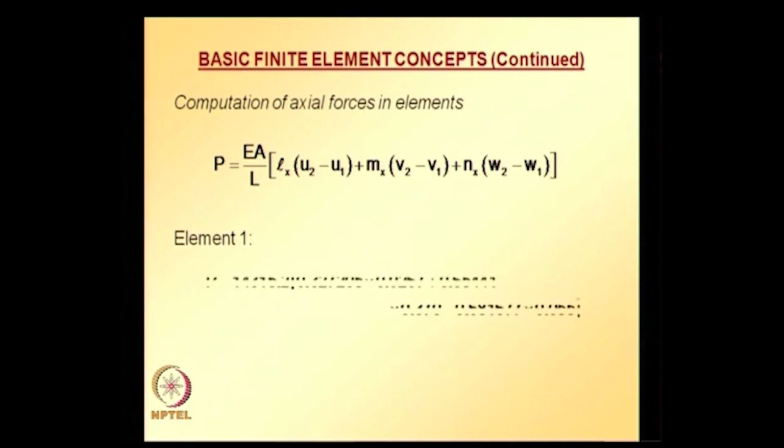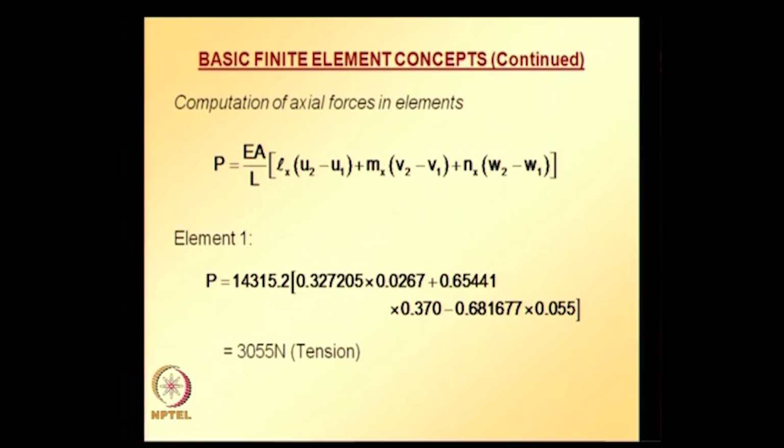For element 1, applying this equation and noting that for element 1 local node 1 is the same as global node 1 and local node 2 is the same as global node 4, with that understanding the axial force in element 1 is given by this, and it turns out that this element is in tension.